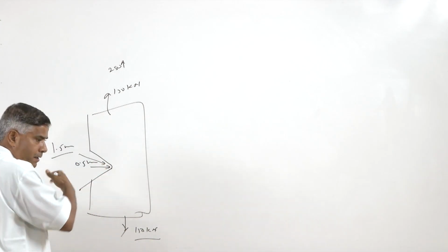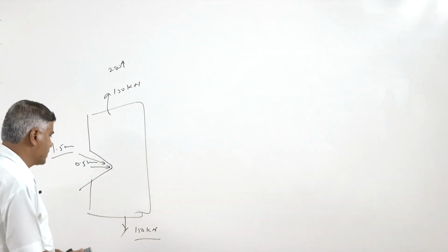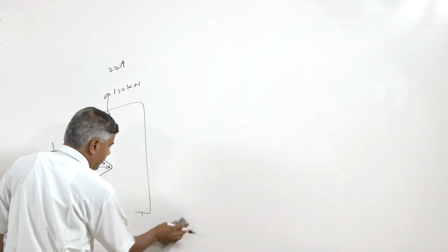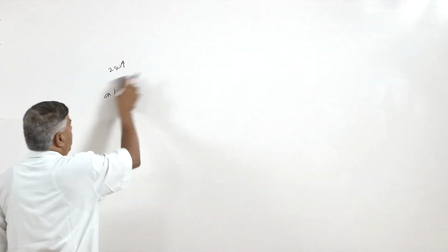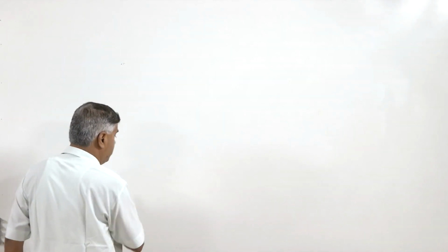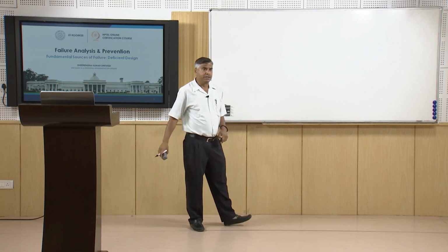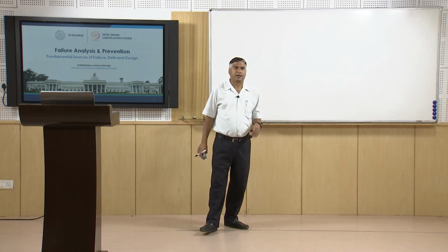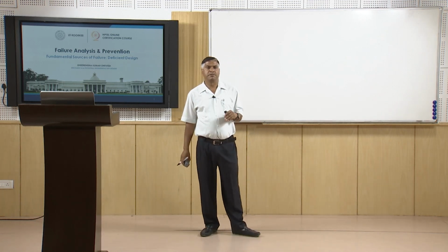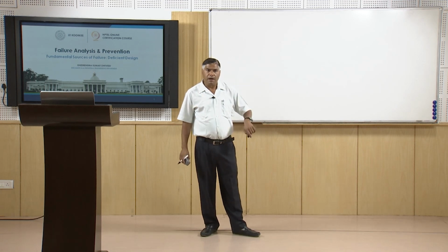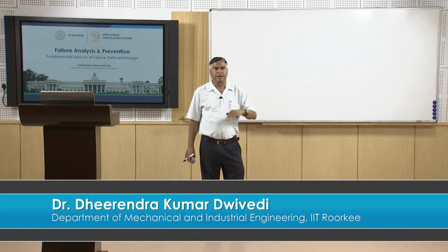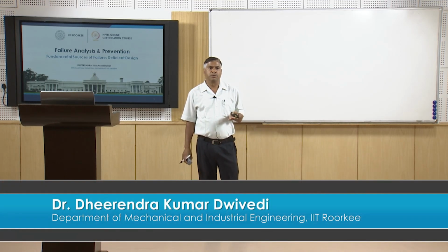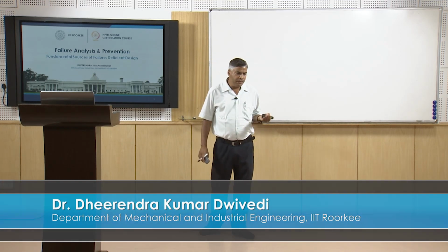and in that case it may require a different radius at the crack tip for avoiding the unnecessary too high stress concentration, so that the premature failure of the component can be avoided. So, presence of stress raisers can be critical for more severe conditions as compared to the earlier service conditions. Now, in light of these points, we will be taking up one case study where the engineers